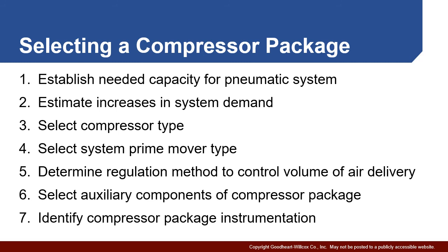In terms of your prime mover, by far the most common type of prime mover is an electric motor, but if you're in an environment where you don't have access to electricity, an internal combustion engine or gas turbine is a possibility. Or if you're in an environment where you have, for example, steam, a steam turbine might be an option in a large industrial environment. So a lot of choices there, but a lot has to do with what you have available. You are going to have to be able to control the volume of air delivered. We just talked about your various options there. That's somewhat tied to the prime mover, tied to the environment, tied to your efficiency requirements.